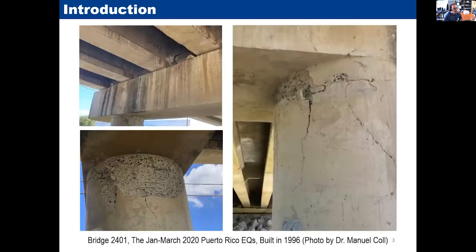So you might all know that the current design philosophy in AASHTO is that it is okay that the bridge after a moderate to severe earthquake gets damaged, but it's not okay if it collapses. So based on this design performance, it is totally acceptable that bridge columns get damaged. Why columns? Because columns are by design the weak link in the overall bridge system.